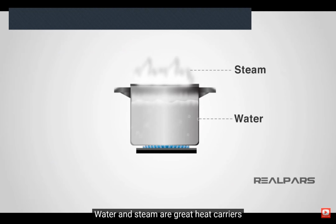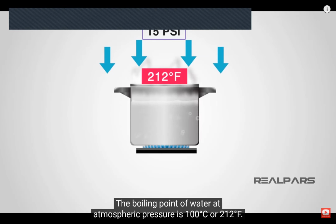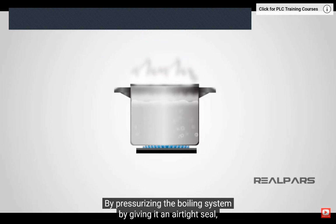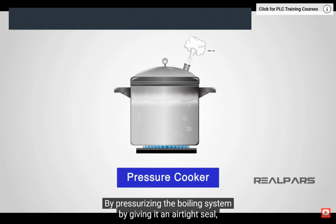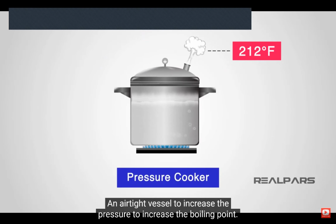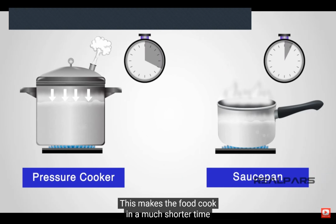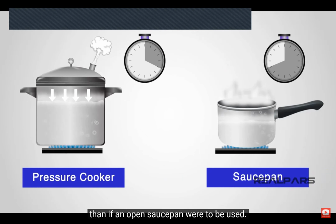Water and steam are great heat carriers and are not damaging to our environment. The boiling point of water at atmospheric pressure is 100 degrees centigrade, or 212 degrees Fahrenheit. By pressurizing the boiling system, by giving it an airtight seal, we can actually increase the boiling point. This is how pressure cookers work. An airtight vessel to increase the pressure, to increase the boiling point. This makes the food cook in a much shorter time than if an open saucepan were to be used.